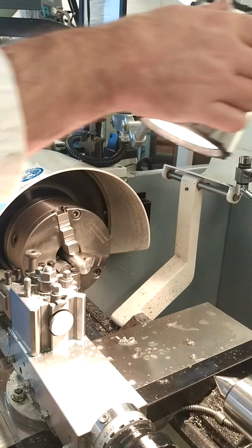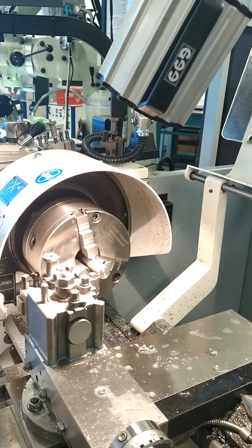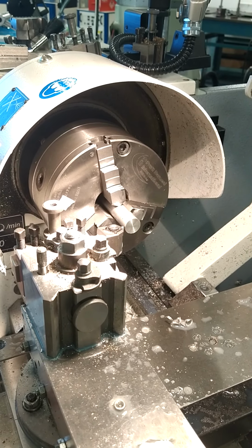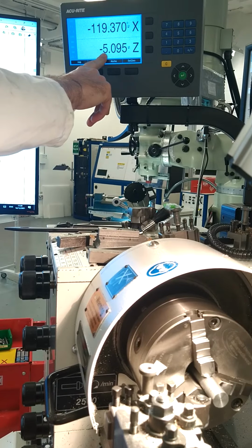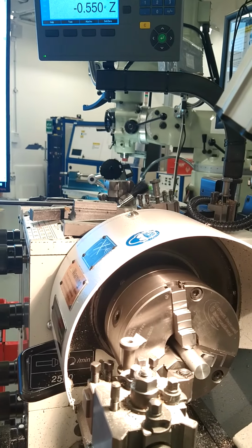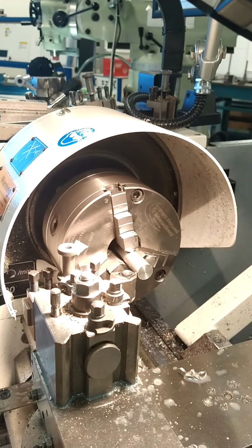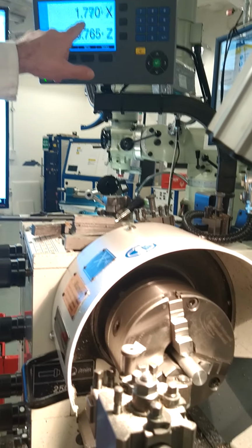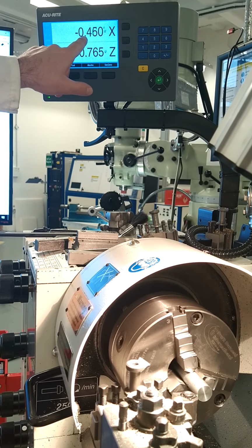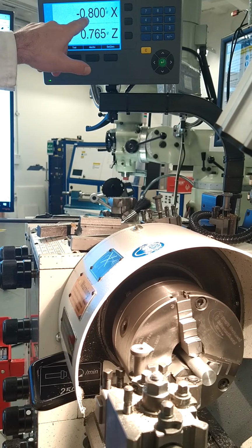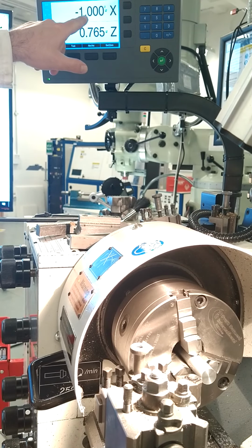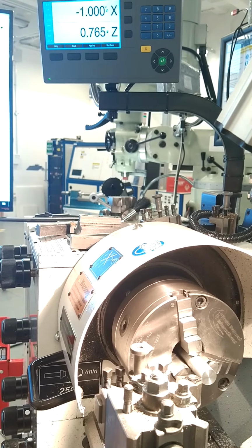That will allow us to travel. If we want to reduce down the length by 5 millimeters, that would bring it down by 5. And to reduce down the X, the diameter of the bar, you touch the tool off the work, zero the X, and enter. So now we're reducing down the diameter as we adjust in the cross slide to 0. Now we'll take it down by 1 millimeter. So power on our lathe now.